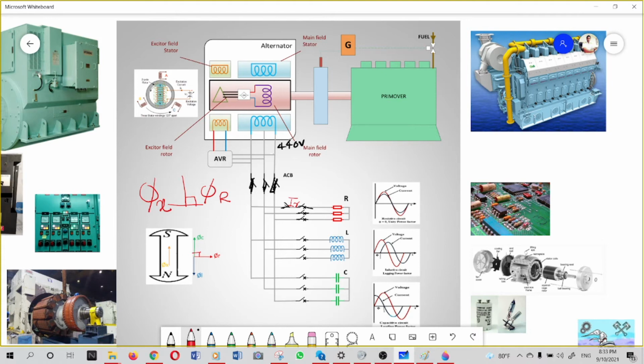As far as the magnetic field strength is constant, the induced EMF, d phi by dt, is not changing, so the EMF will not be affected. But they have found that, due to this new magnetic field in another plane, there will be a magnetic interaction which will cause a retarding torque on the alternator rotor.